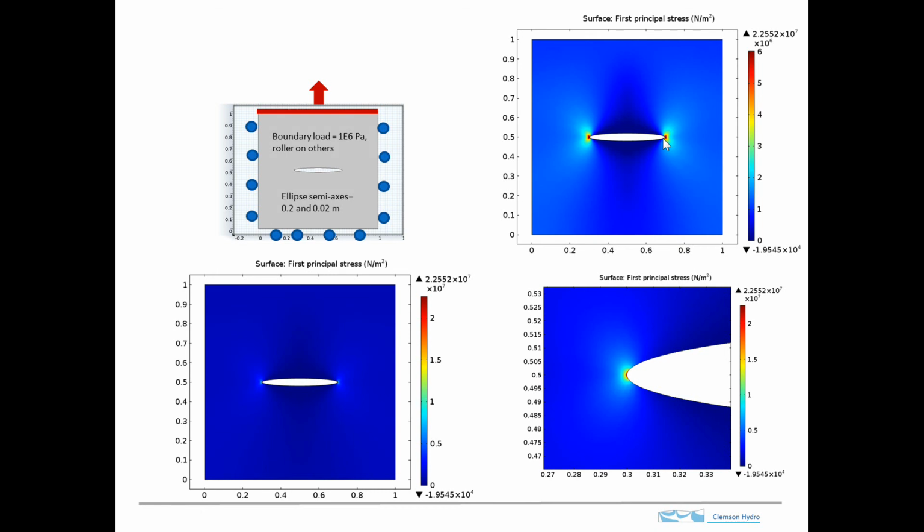And what happens is these micro cracks will concentrate the stresses at their tips, just like the stresses are concentrated here. And so the net effect of this is that these micro crack flaws concentrate the stresses, and when a load is applied to a material, the stresses that are concentrated at the tips of these flaws are the place where the material will fail first. So the material fails here first, and the bonds are broken, and this crack propagates out like this.